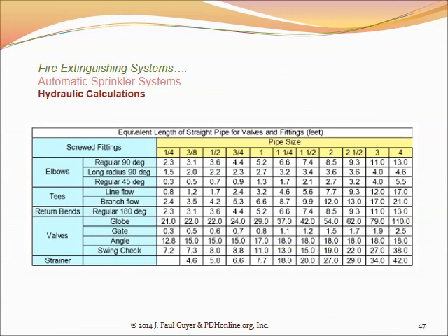And the fire design area is the 3,000 square feet in these illustrations here. And all fire sprinklers are rated by the manufacturer. So the manufacturer in the catalog will say, well, my sprinkler head will discharge so many GPM per square foot over a 15 by 15 square foot area or 20 by 20 square foot area, as long as you provide it with water at a pressure of at least, say, 20 psi. So you've got 50 psi coming in, and you need to have 20 psi where the fire breaks out.